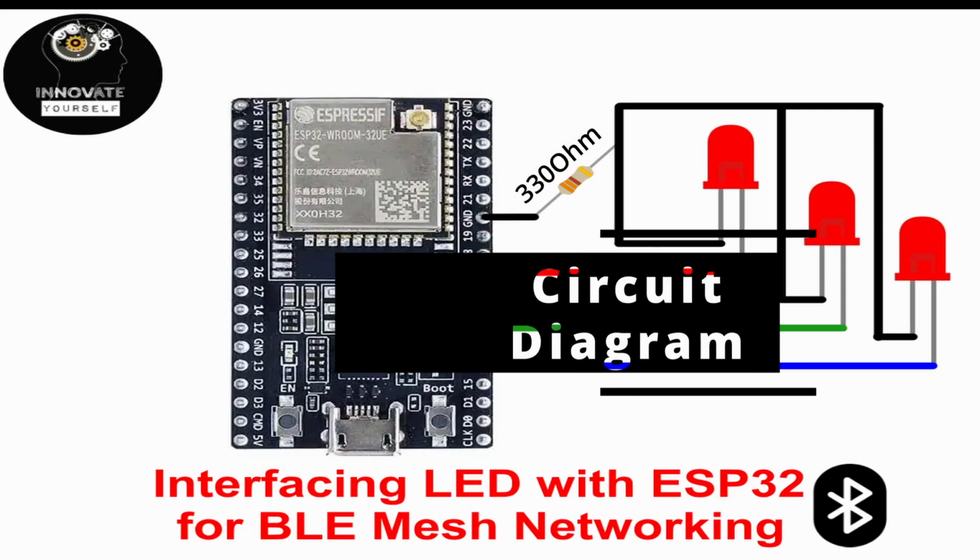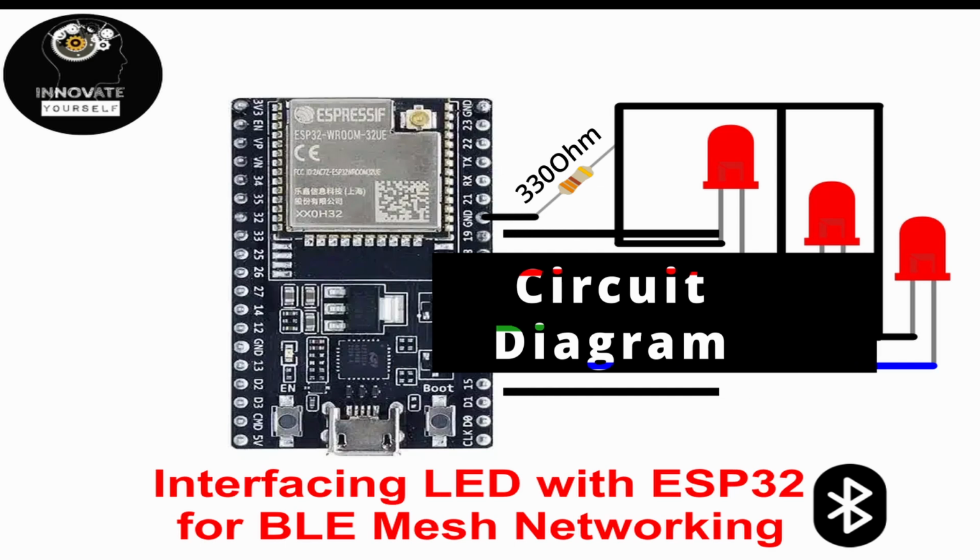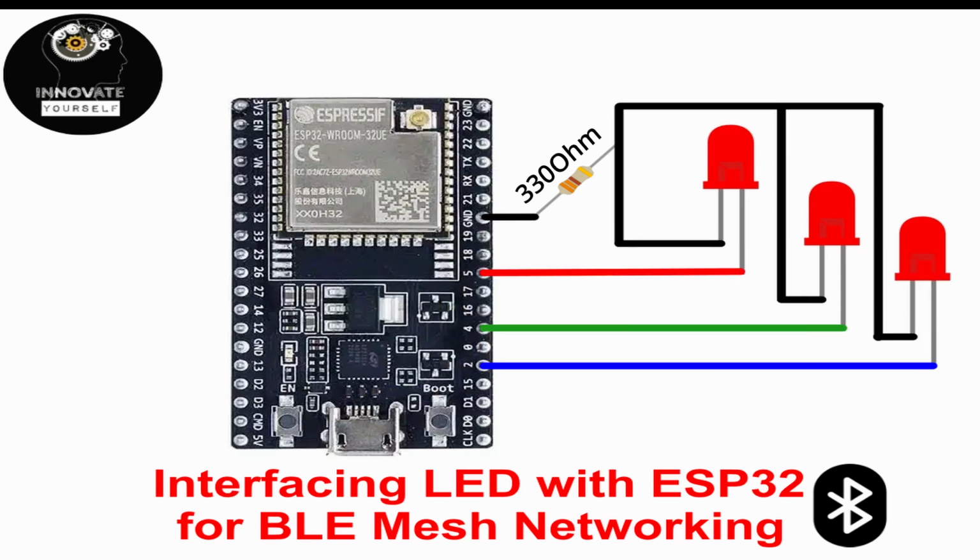Alright everyone, now you have to make the connections of your ESP32 with all the three LEDs which we will be controlling using the BLE Mesh program. So you have to make the connections in this way. We will be using pin numbers D2, D4 and D5, and we will connect the LEDs to those, which we will be controlling later on. Now let's move ahead and understand the coding so that we can make the final program.